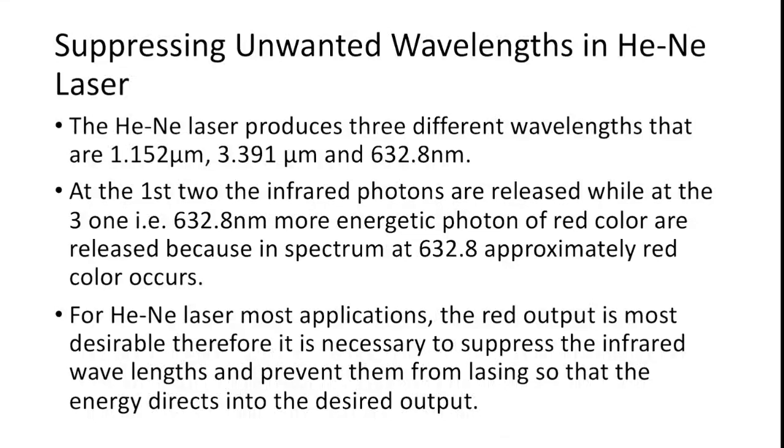Importantly, note that CO2 lasers use carbon dioxide as well as helium and nitrogen as the active medium. So here it uses carbon dioxide as well as helium and also nitrogen. So, the characteristics of CO2 lasers. A CO2 laser produces a far infrared beam at 10.6 microns. It can also operate with an output of 9.6 microns, but this output is not very common.